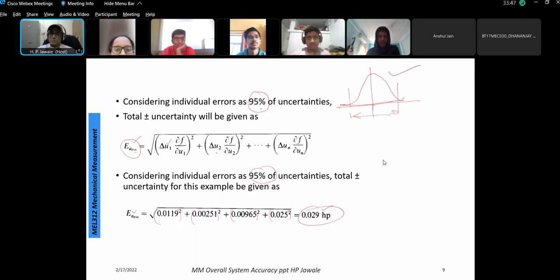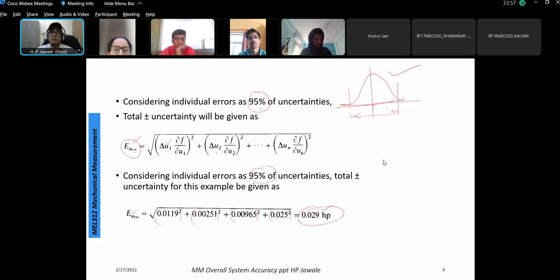Say in this case, if I am saying the final error propagated should not be greater than 5%, then I must assure that the measurement of the force shall be within the given accuracy. There should be some controlling value for the measurement error on the force, the measurement of the revolutions, the measurement of the time, and so on. So I must select the proper measurement devices.